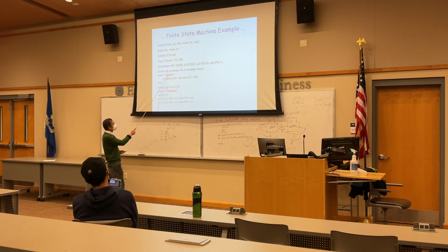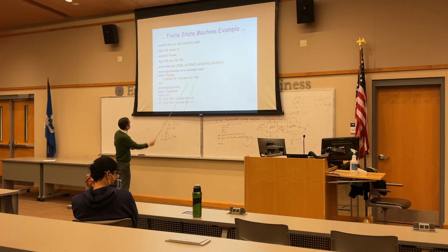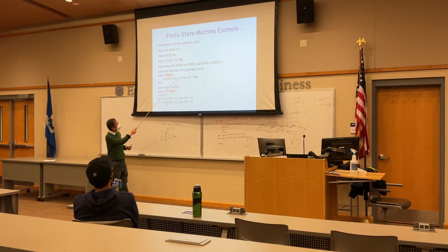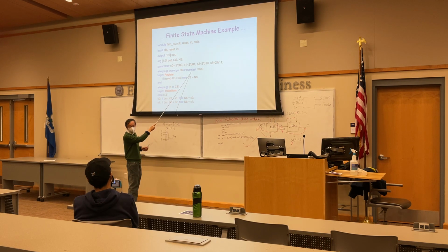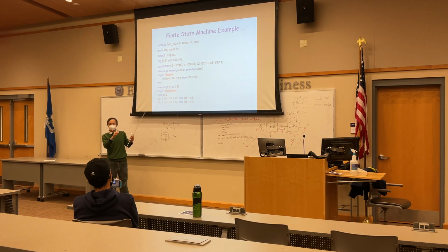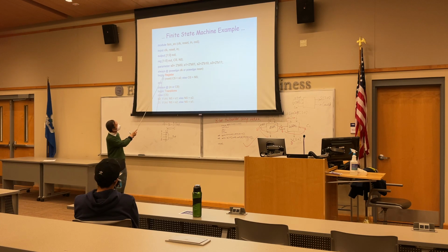Now, either reset initially or pass the next state to the current state when the clock edge comes. So in this way, tomorrow becomes today. Always at positive edge clock or positive edge reset: if reset is activated, reset to S0. Otherwise, at this clock positive edge, the next state becomes the current state. That's the reset and the state transition.